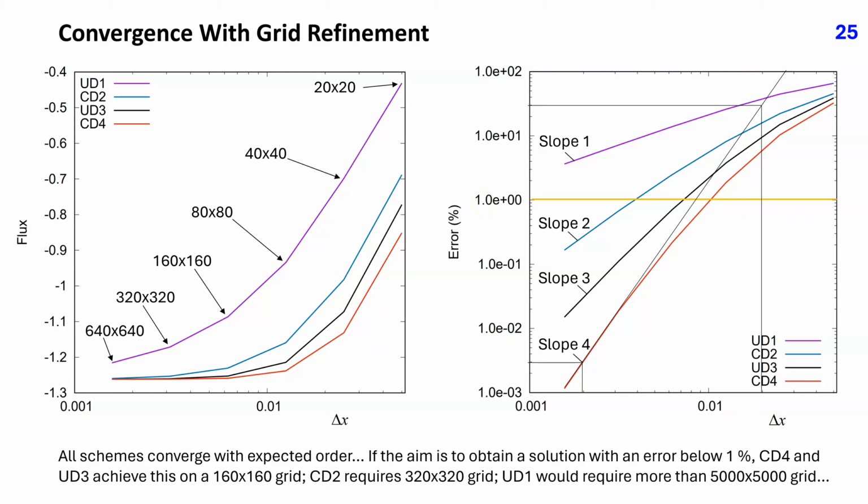Here we are looking at the total diffusion flux through the west boundary. The local heat flux per unit area at the boundary grid nodes was integrated along the whole boundary using the fourth-order Simpson rule for all schemes. The plot on the left shows how the total heat flux varies with reducing grid spacing. The high-order schemes converge rapidly toward a grid-independent solution, while the solution from the first-order scheme still contains a large error even on the finest grid.